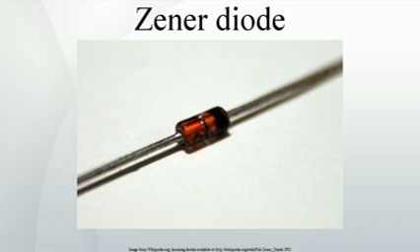Subsurface Zeners. A subsurface Zener diode, also called buried Zener, is a device similar to the surface Zener, but with the avalanche region located deeper in the structure, typically several micrometers below the oxide. The hot carriers then lose energy by collisions with the semiconductor lattice before reaching the oxide layer and cannot be trapped there. The Zener walkout phenomenon therefore does not occur here, and the buried Zeners have voltage constant over their entire lifetime. Most buried Zeners have breakdown voltage of 5 to 7 volts. Several different junction structures are used.